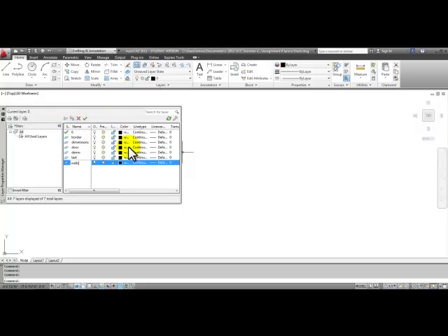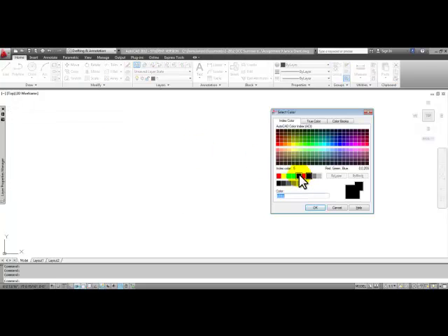And then we're going to change the color based on what it says on the posted drawing. Here we're going to, for the border layer, pick on the word white and change it to blue. Blue is going to be here underneath the index colors. It's color 5. Pick blue and pick OK.